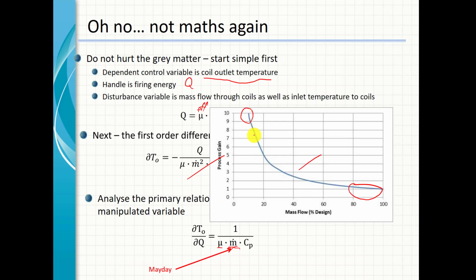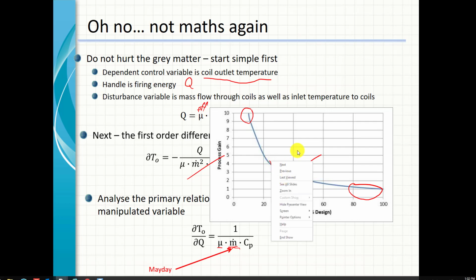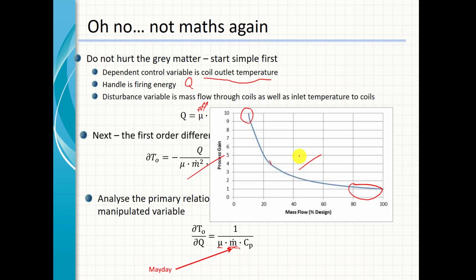So you are not going to be able to put your temperature loop into automatic because it simply will not control. So you often find when people start up the plant, the operator gets to about this point, some minimum load, and wants to put the loop into auto, and it starts becoming oscillatory, or even I've seen some operators starting over here, which becomes a problem as well.